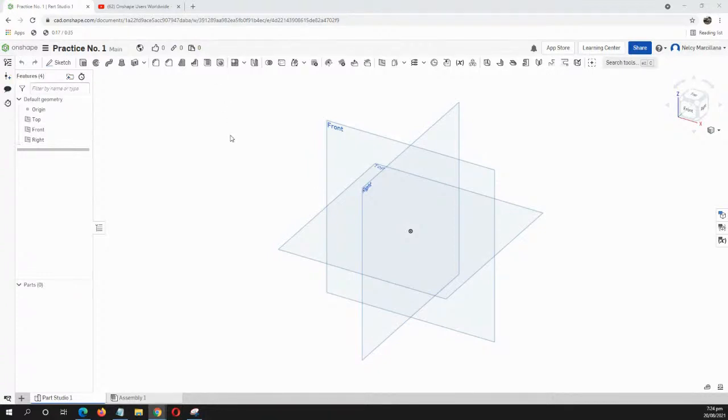Okay, so our sketch is in millimeters. By default, Onshape is in inch. So let's head over to the Document menu, selecting Workspace Units. We have different units of measurement. For this one, let's use millimeter. Leave all by defaults and click the green check mark.